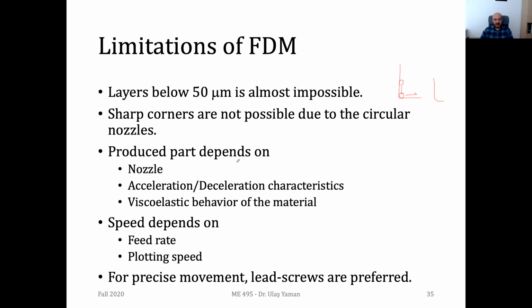Another thing about the products, their quality obviously depends on the nozzle type, the quality of your nozzle, whether you have any clogged material, or the acceleration and deceleration characteristics of your used motors. For instance, this might be the S curves. If this is speed versus time, this is your acceleration characteristics, and at that point, acceleration starts.